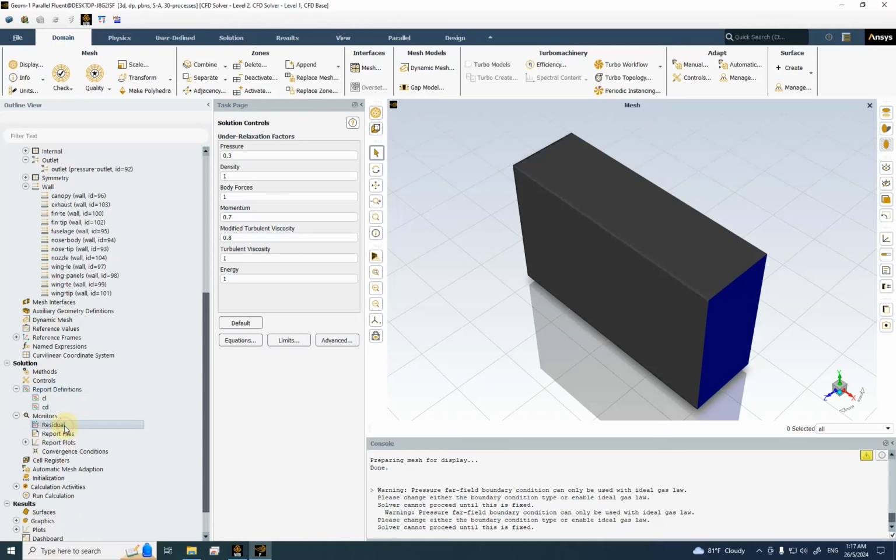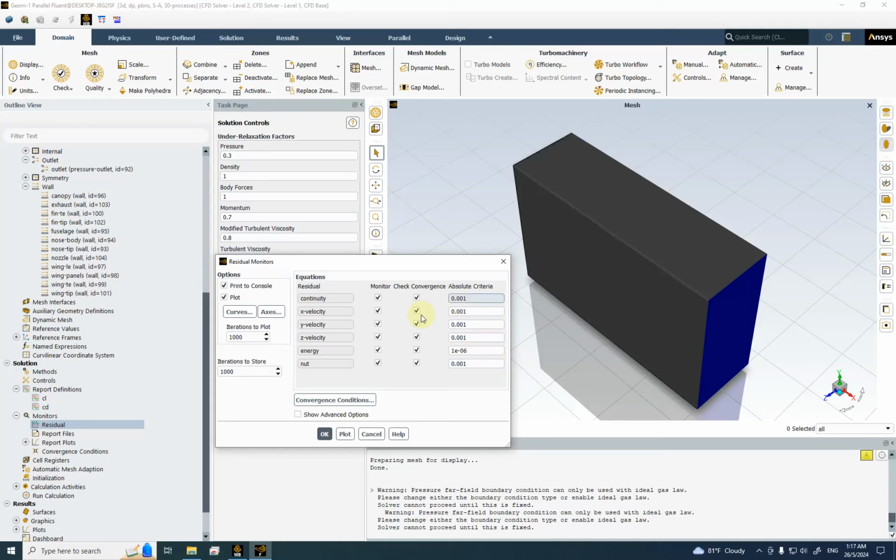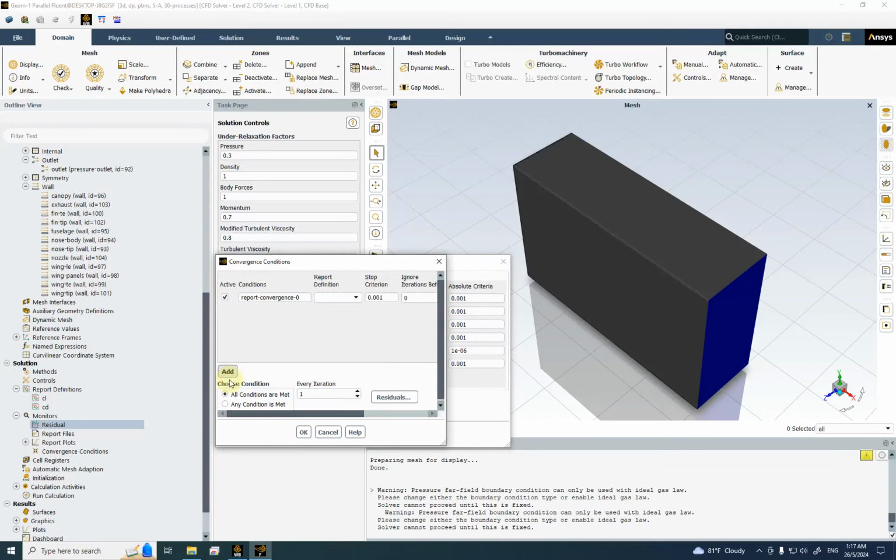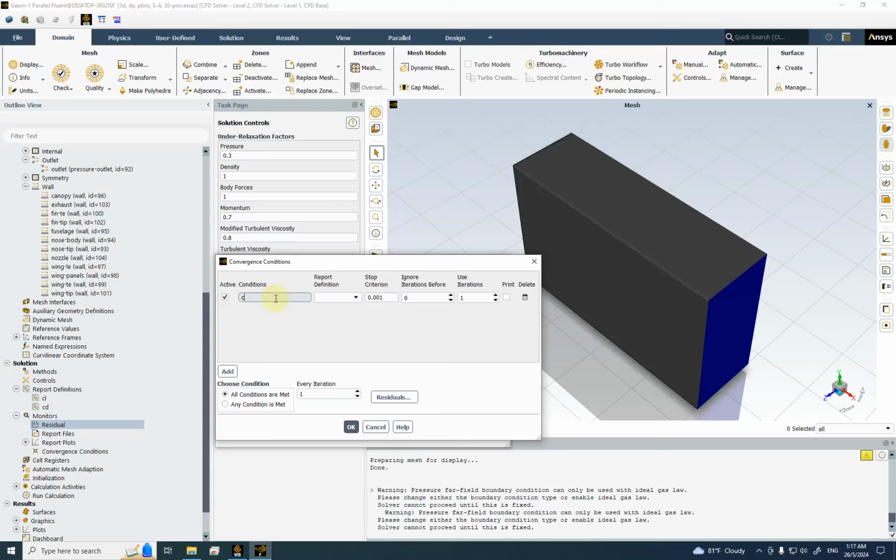And then here the residual. Okay, I want to make sure that the CL and CD will reach, this is the difference, okay, the delta CL, the change of CL is less than 0.001, okay, every 20 iterations, then only I consider the solutions converge.